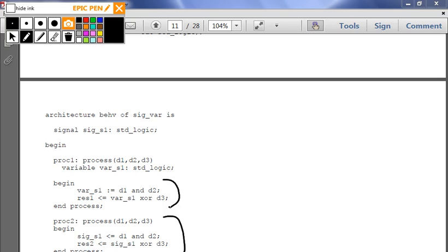And then in the actual lecture that I did last class, I had some code where we actually used two components, an AND gate and an XOR gate, where I had coded 5 nanoseconds of delay into both of them. Do you guys remember what happened? What was the error that happened? Yeah, we had the little quick pulses. The reason is that we had the 2 inputs going to the AND gate, but we were already propagating the 3rd input to the XOR gate.